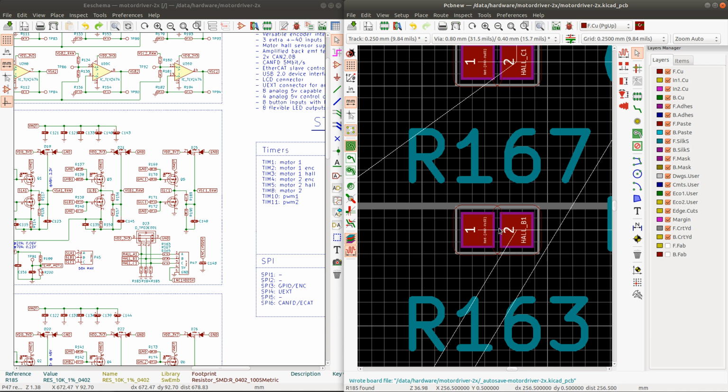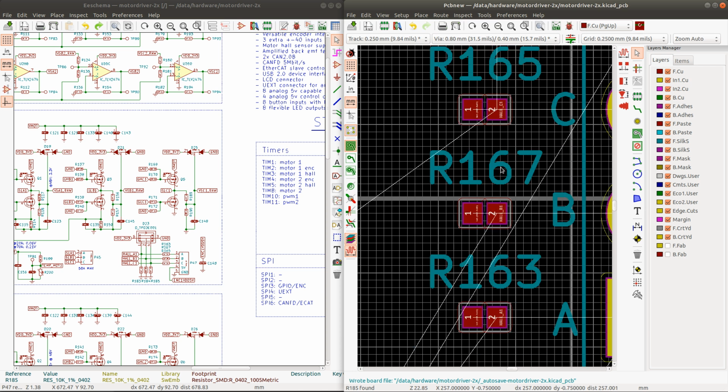But for this PCB, I decided that I'll use the KiCad default footprints, because I had some problems with the footprints that I've generated. When the components were soldered, sometimes the components would go on the side because the size of the footprint wasn't precisely correct. So it's better for this board to use the default footprints, but once I've fixed my own footprints, then I can use the footprints with proper courtyard. Did that answer your question, Nicholas? Or did you mean something else?